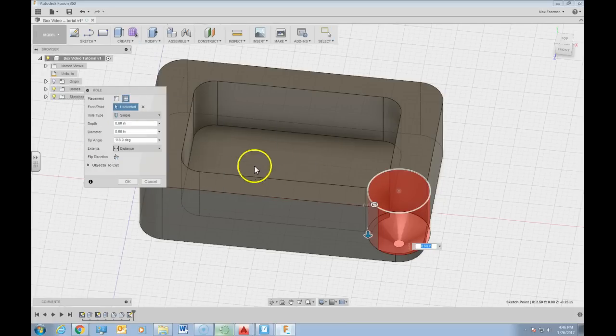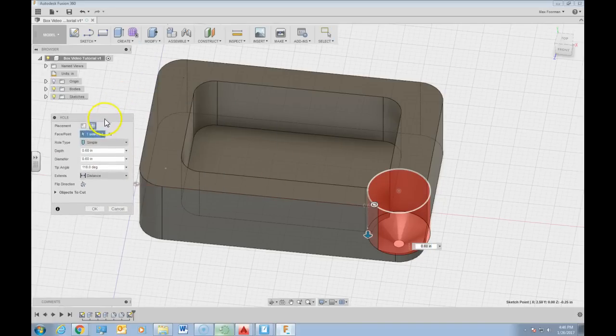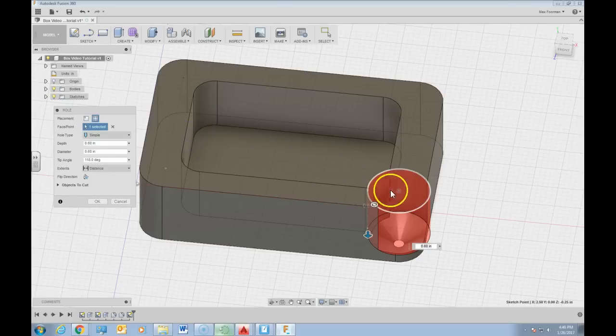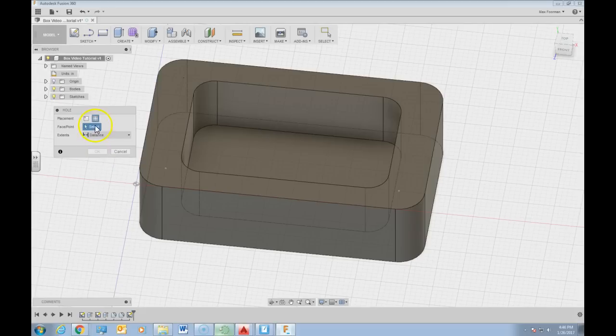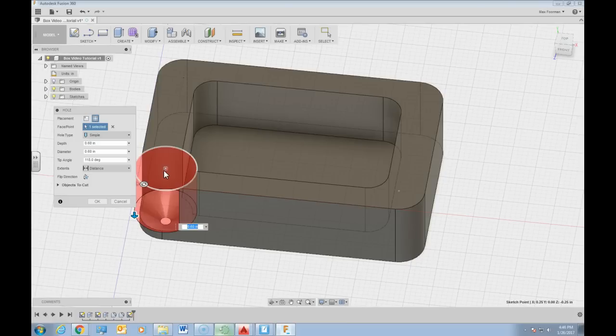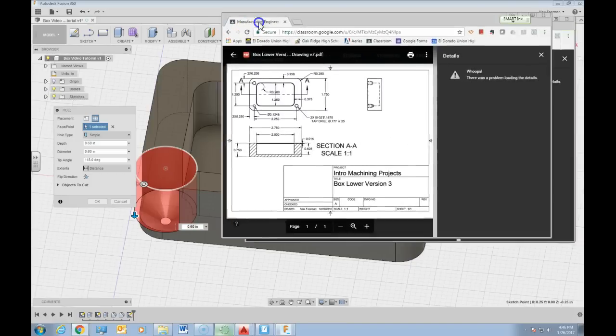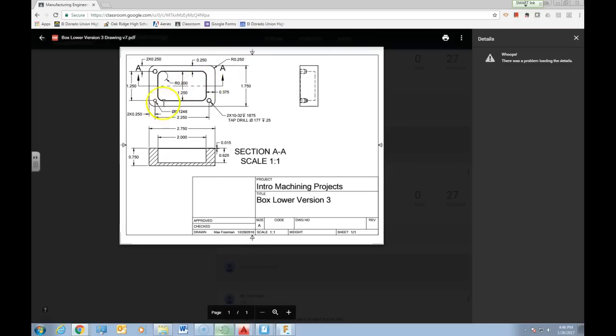So now here's hole. Whoa. What happened here was, I had gone into this with that point selected. I don't want to work with that hole quite yet, so I'm going to unselect that. Now instead of that one, I'm going to click this hole right here that's going to relate to this simpler hole feature here. That's a pretty small diameter hole compared to what I've just ended up with. It's going to be a diameter of 124 thousandths and 8/10ths of a thousandth of an inch.